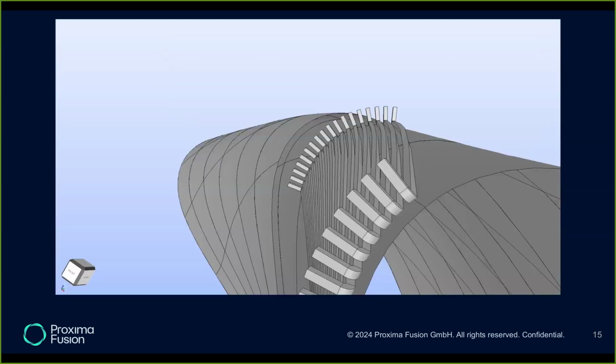And these pipes can be quite tricky to design, can be quite complex. You see, for example, in this screenshot, this pipe comes in straight and then has to do some twisting because you want the lower side of the pipe to be as parallel as possible to the surface, because otherwise you lose a couple of millimeters there. And in this kind of application, even a couple of millimeters can make the difference between a solid and a fluid wall.